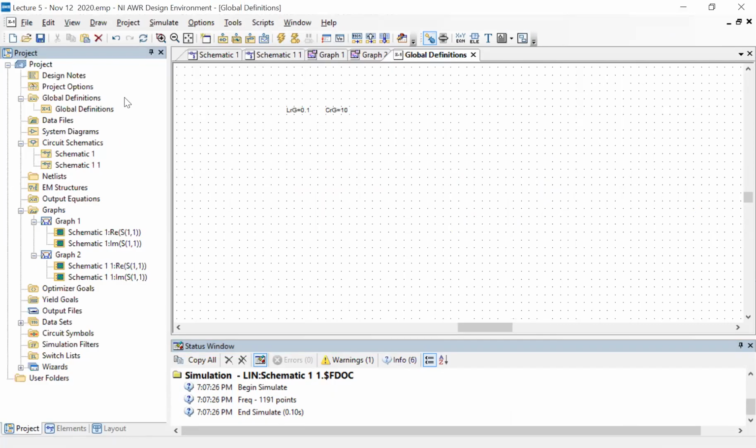Later on, I will also show you how you can actually define measurement equations. This thing is surprisingly powerful. You can actually define an array here. You can do all kinds of mathematical operations. There's a whole list of functions you can apply. So you can do quite a bit of computation. So maybe you have an expression for Z, and you want to compute gamma, but as a formula rather than using the S11 measurement, you can actually do that. And all of these calculations are done in the complex domain, because all of these quantities are in general complex. Okay, so this is quite handy. So as and when I get an opportunity to introduce these kinds of additional concepts for using Microwave Office, I will keep doing that.